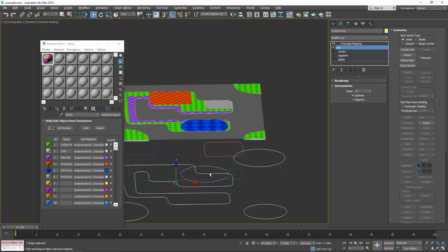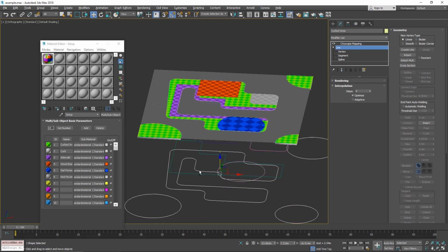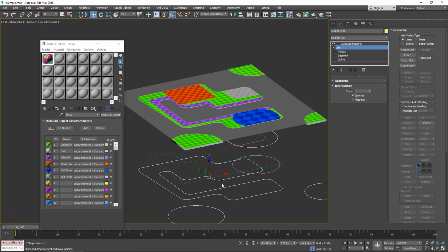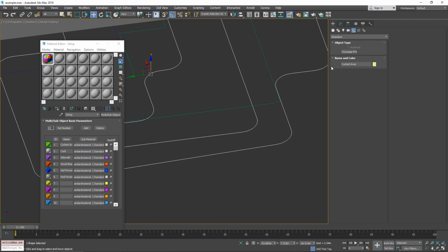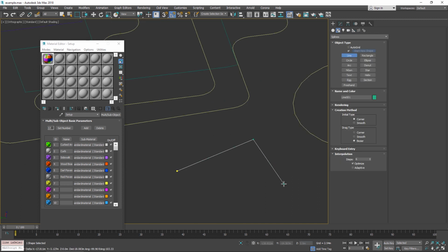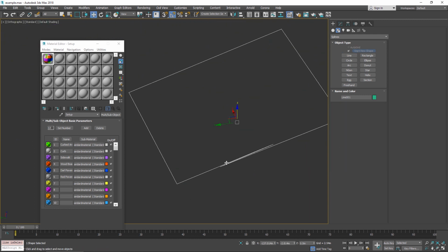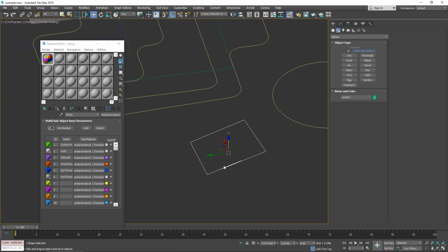If you're importing any splines or geometry from CAD, it should be cleaned up. The vertex count has to be reduced to as low as possible. The splines shouldn't have any kind of self-intersection. When I say self-intersection, let me just show an example. In CAD models, you have things like that sometimes, which is not visible. So this might have a problem because it's just self-intersecting. Things like that have to be corrected.